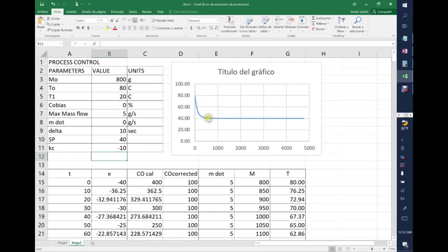It just got quickly to the value of the set point. I would say here with 500 or so. So it seems to me that -10 might be better. It gets the job done faster. How about -20? Maybe. Minus 20 seems still okay.